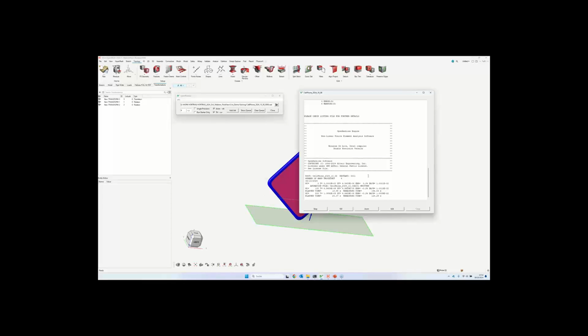Anyway, I have also shortened the simulation a little bit to just 2 animation files, because the rest I already ran in advance and provided to Francois. So we will just see the first animation files. After the simulation with OpenRadioss is successfully done, the converter will start and convert the animation files which are created here. So you can see them dropping now into my folder.